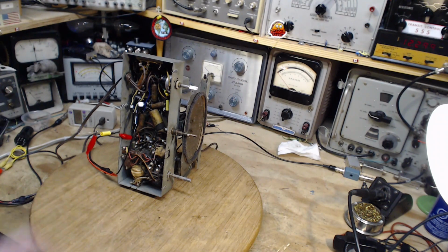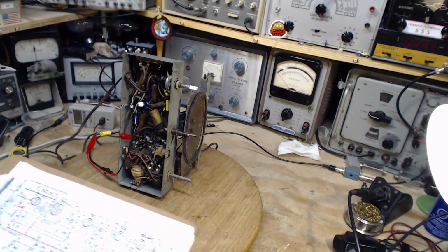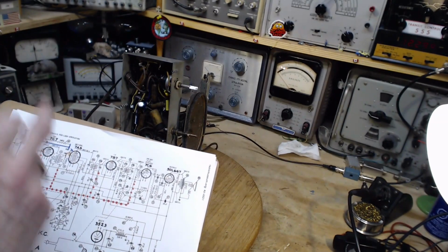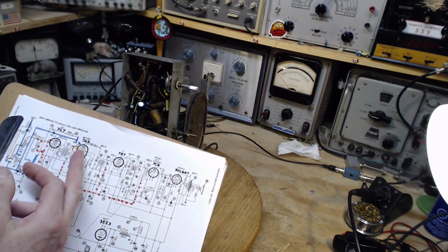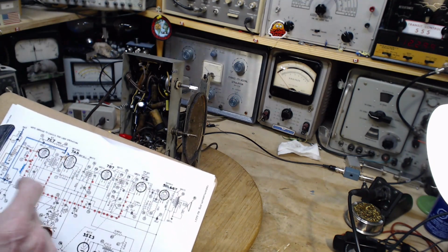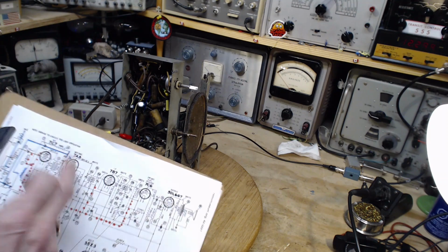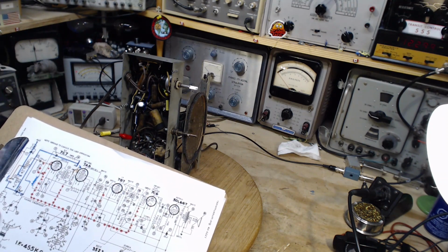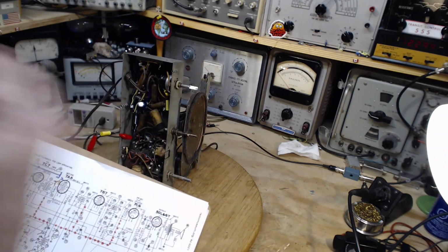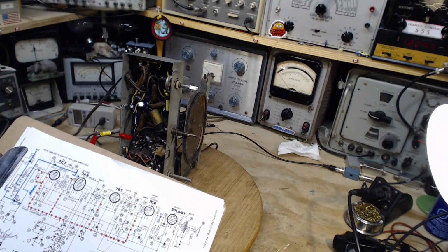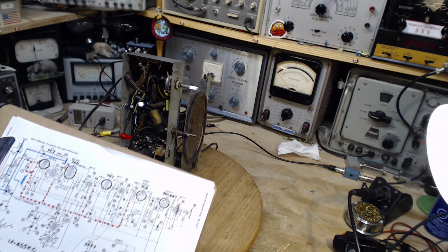This is a very strong signal being put onto this tube. So what could be wrong beyond there? After this tube, the signal's been converted down to the IF frequency to run through the IF transformers. So, weak local oscillator? If you have a weak oscillator, you get a weak output. Well, yeah, I guess we could look into that. That's not hard to look into.